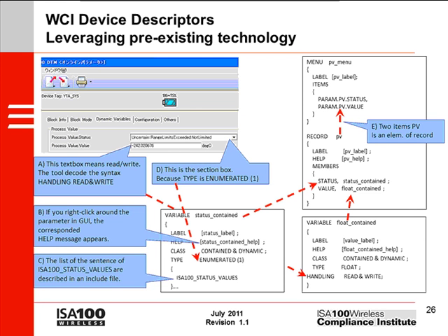Okay, this slide shows one simple example of how a Foundation Fieldbus device description can be applied to an ISA100 device. The general idea is that a user interface is automatically generated based on material provided in the DD file. For example, there is a selection list on the user interface, and the available selections are determined by the device description. My main point is that this will look very familiar to people who are well-versed in Foundation Fieldbus.